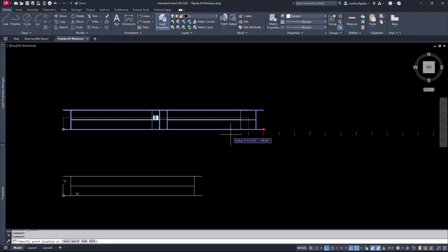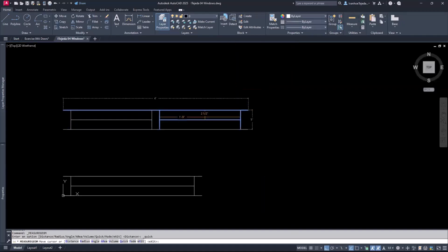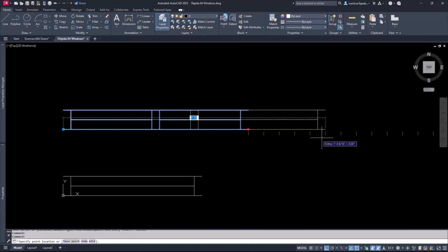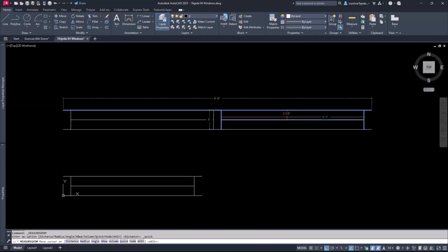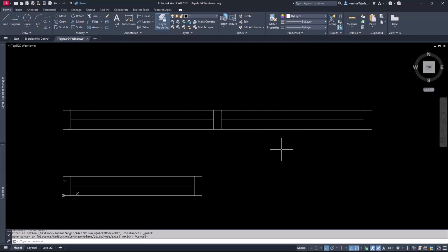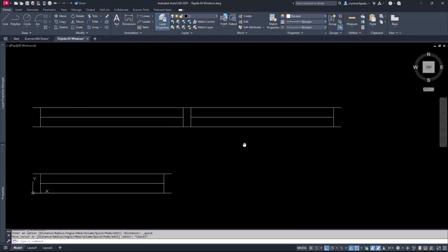And now when I go to stretch it, I click here. And now you see that's as small as it's going to be, 4 feet. And now if I look at the distance, let's see, measure. 1'9", 1'9". Okay, tap the escape key. Select it. Click on the distance and bring it out to any distance that you want like that. Measure again, the distance here, 3'1", 3'1". So it is stretching as required, which is half the distance.